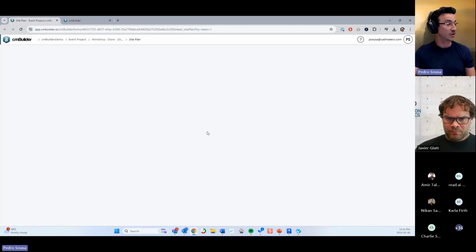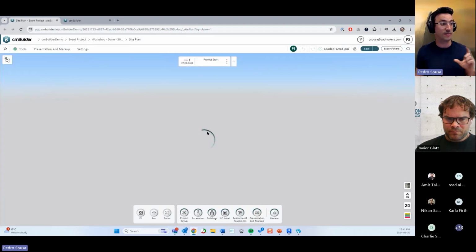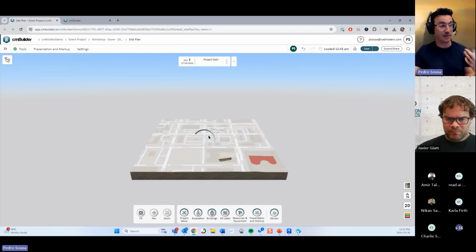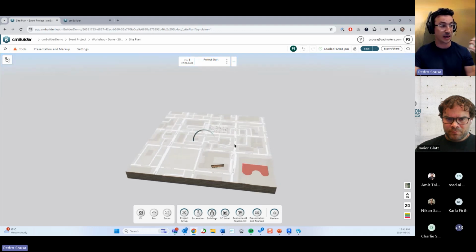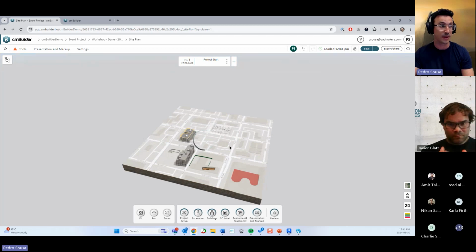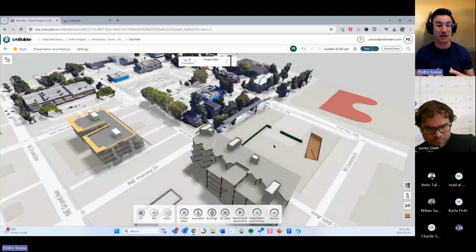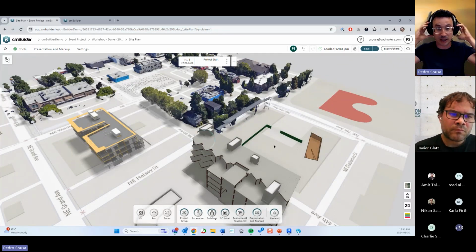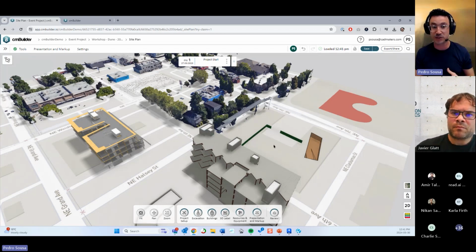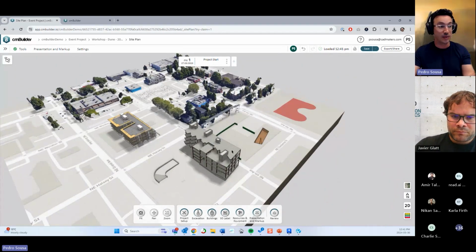So the idea is that the default filters that you had before with IFC files are now applied to Revit files as well, which doesn't look like much, but it's a great improvement because with Revit files, if you just drag and drop them without opening that file beforehand, you never know what you're bringing into the software, right? You might bring in parts that are hidden, parts that you didn't filter beforehand, and so on and so forth. You couldn't apply those filters before, and now you can.